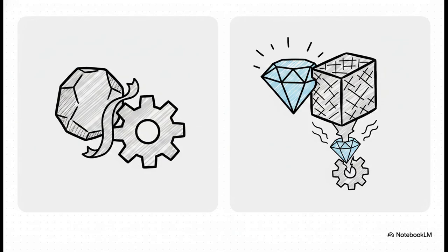We generally split these tiny cutting tools into two main camps. First up, we've got conventional abrasives like aluminum oxide and silicon carbide, which are used for your everyday metals and alloys. Then we have the super abrasives, cubic boron nitride and diamond. These are literally the hardest materials known to humanity, reserved for highly specialized jobs. But here's a totally surprising fact. You actually cannot use diamond to grind standard steel. Why? Because at the extreme temperatures of grinding, the carbon in the diamond physically dissolves chemically into the iron of the steel. So matching the exact right microscopic tool to the right material is an absolute science.